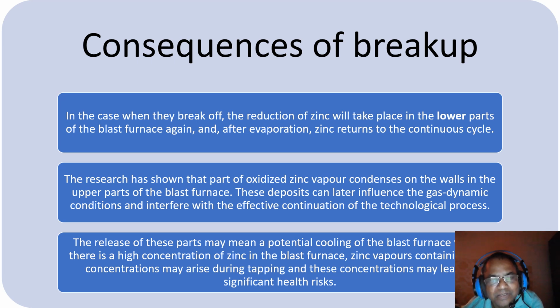This causes cold hot metal from the tap hole, asymmetric metal temperatures from tap hole to tap hole, and many irregularities in the casting, in the wind acceptance of the furnace, and several other reasons.